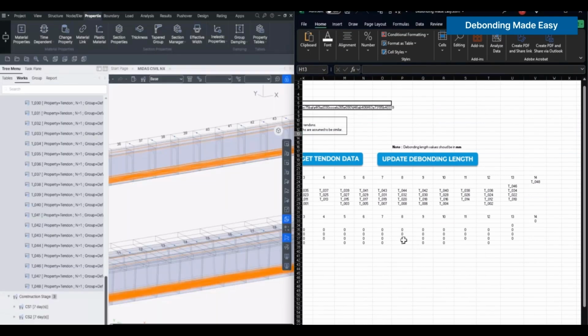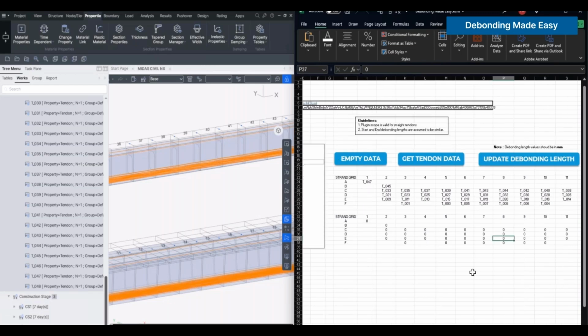Now to update the debonding lengths, again there are various rules, such as the number of strands to be stressed in a single line adjacent to it. So we can just follow those rules which an engineer is familiar with. Enter the debonding lengths over here, 3000, whichever. The units provided over here should always be in mm. This is just a note of how the scripting is conducted.